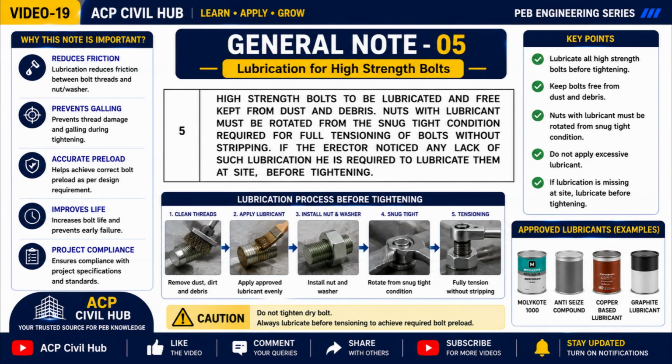During tightening, the nut should rotate smoothly from the snug-tight condition until the required bolt tension is achieved without damaging or stripping the threads. If the erection team finds that the factory lubrication is insufficient or has been removed during handling or storage, the bolts must be lubricated again at the construction site before final tightening.